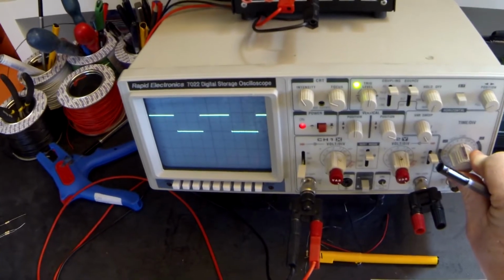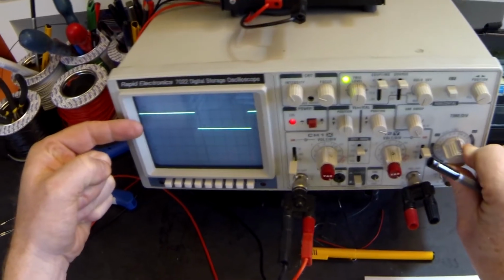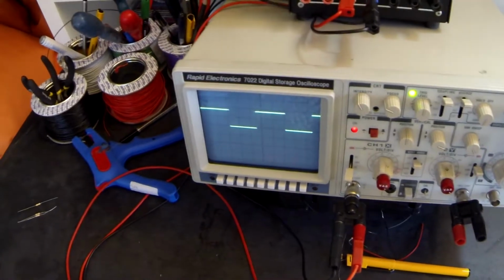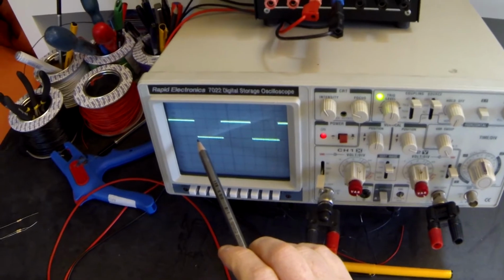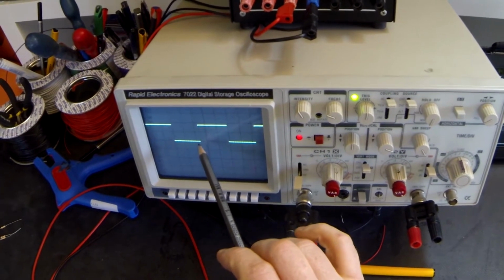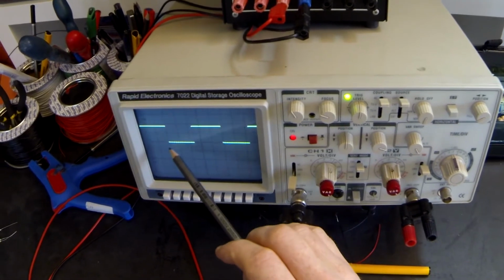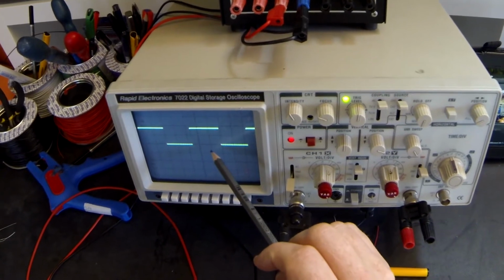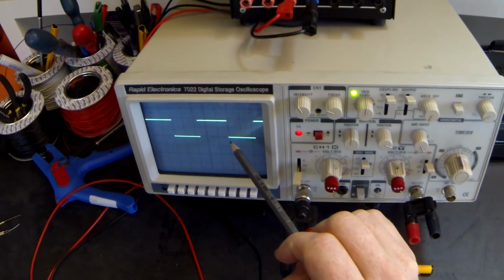So I'm going to do it so I only see one waveform. Now, once again, we can't see a whole waveform here, so that's the setting that I need to go on. I can position it so that I can make my measurements easier. So I've started my waveform at the bottom here. I'm going to measure one waveform, which is a low plus the high. That is one waveform from there to there. So that is 1 division, 2 divisions, 3 divisions, 4 divisions. That is about 4.9 divisions if I'm going to try and be really accurate here.